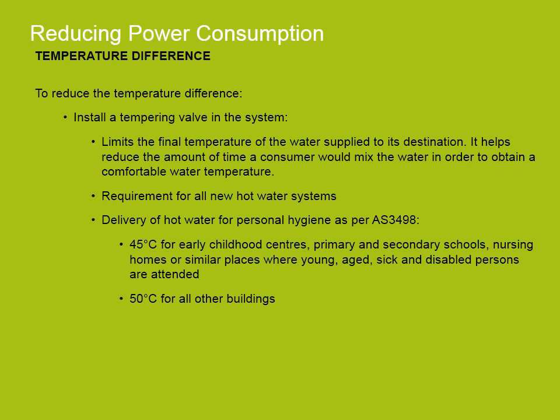It states that for early childhood centres, primary and secondary schools, nursing homes or similar places, the delivery of hot water for personal hygiene shall be limited to 45 degrees Celsius. For all other buildings, it should be limited to 50 degrees Celsius.